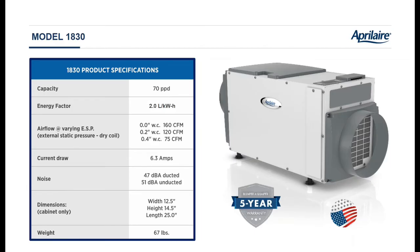But I also want to point out the amount of air that this unit's going to move. That's a key component to the dehumidifier actually being able to achieve that rated capacity. If you've got a portable, it's only moving a little bit of air, maybe 40 CFM. So it's not churning the air in the space. And so it's effectively dehumidifying a bubble of air around it.